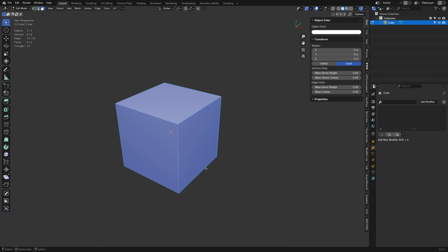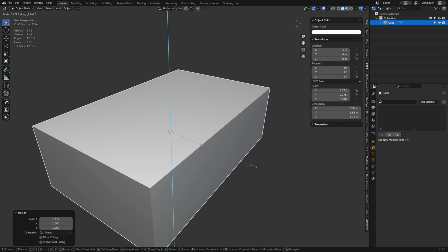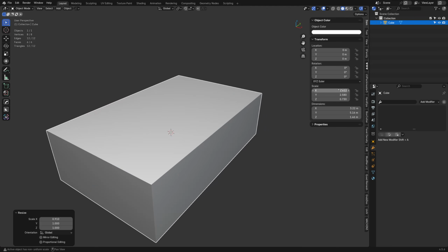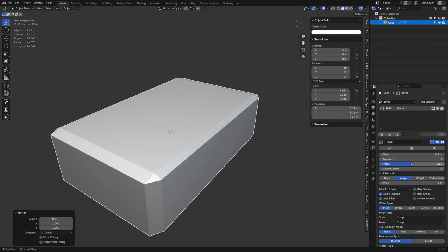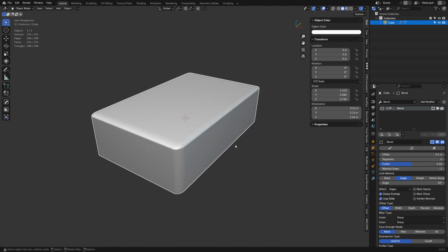And so this shape here, I want to mention something. When you scale something in object mode, say we didn't want to mess around in edit mode a little bit, we get non-uniform scale if the numbers don't match. So if we add a bevel, we add the segment counts up. It doesn't bevel correctly the way you would expect it to anyways.